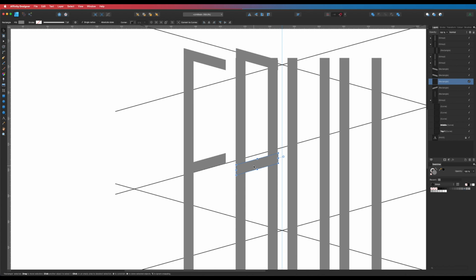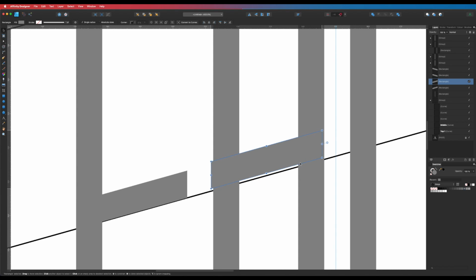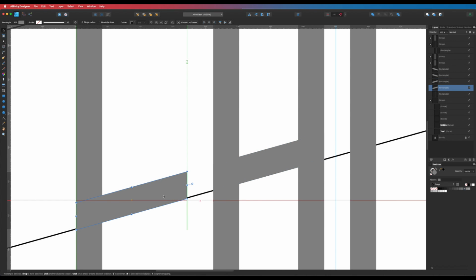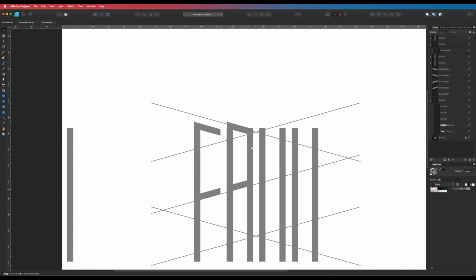Okay, and I actually want this to go up on the inside of this. I'm going to bring this up to this section here so you can see how it's nicely snapping in there. If yours isn't snapping, make sure your snapping tools are switched on up here. You can see where I'm hovering over with my mouse, so just make sure it's nicely snapping over there. I'm going to bring that down just to there so it's covering that little black bit.